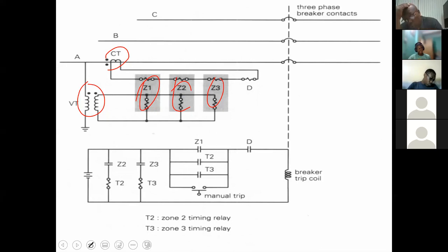So what we have here is that all three coils will become energized simultaneously because it's one fault. We can't experience the fault at different times. Are you with me? So as part of the operation, what we then have are the three instantaneous contacts.